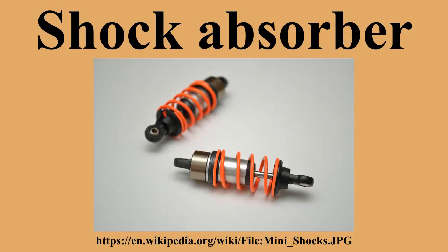Hysteresis of structural material, for example the compression of rubber discs, stretching of rubber bands and cords, bending of steel springs, or twisting of torsion bars. Hysteresis is the tendency for otherwise elastic materials to rebound with less force than was required to deform them. Simple vehicles with no separate shock absorbers are damped, to some extent, by the hysteresis of the springs and frames.